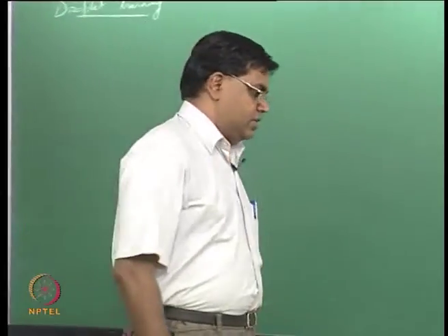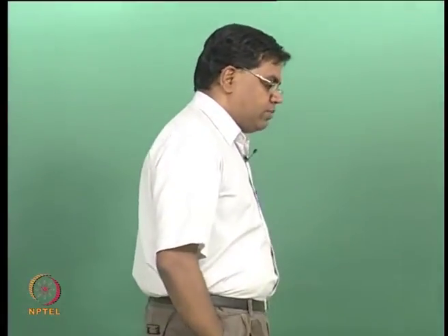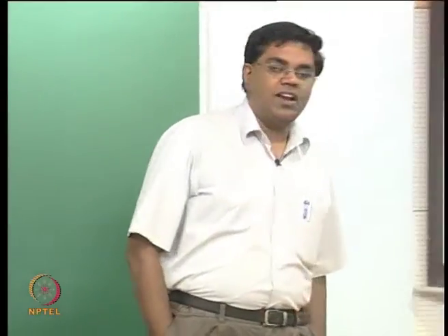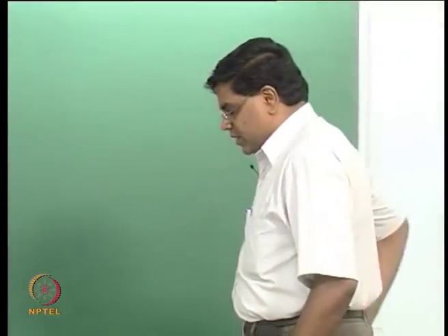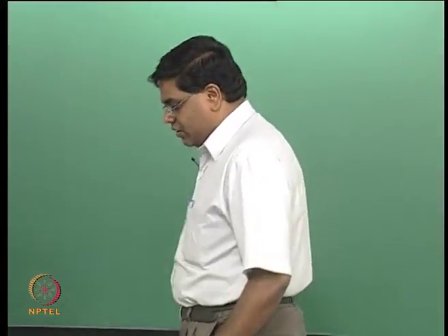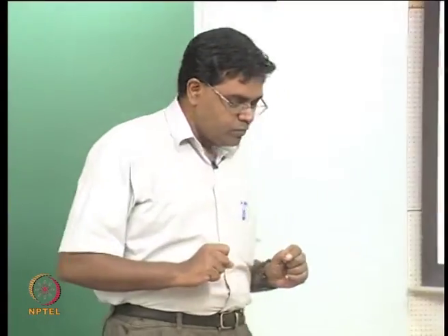You have typically what's called dense sprays, where most of the combustion happens in droplet clouds as opposed to happening on single droplets. But for the sake of convenience at the moment, we will try to analyze a single fuel droplet burning in a gaseous oxidizing ambience. So this is the framework in which we want to do this.